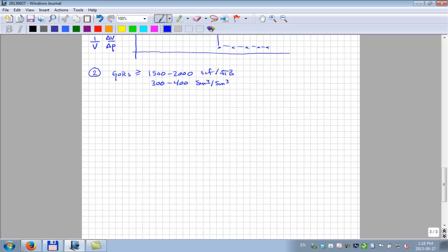But it's also for oils, right? Yeah, so this is going to be oils transitioning into gas condensates. The typical transition GOR from oil to gas is around 3,500 cubic feet per barrel, about 700 cubic meters per cubic meter. It's not an exact transition from being an oil to being a gas, but in that range, between 600 and 800 cubic meters per cubic meter, it typically goes from being an oil to gas condensate as a